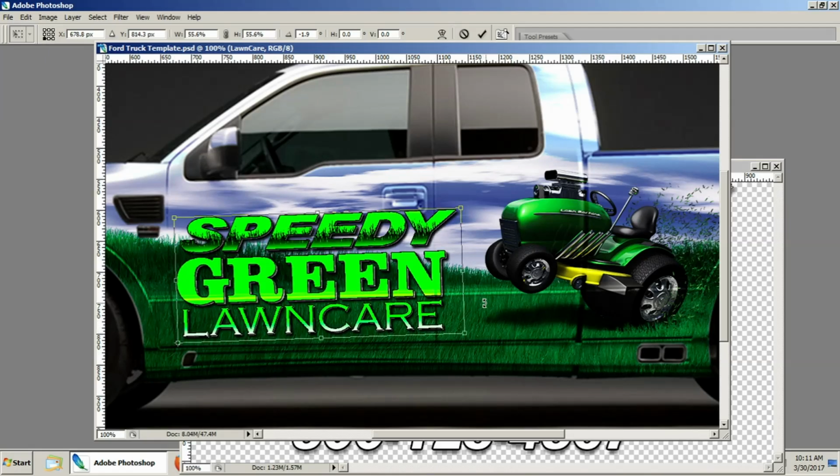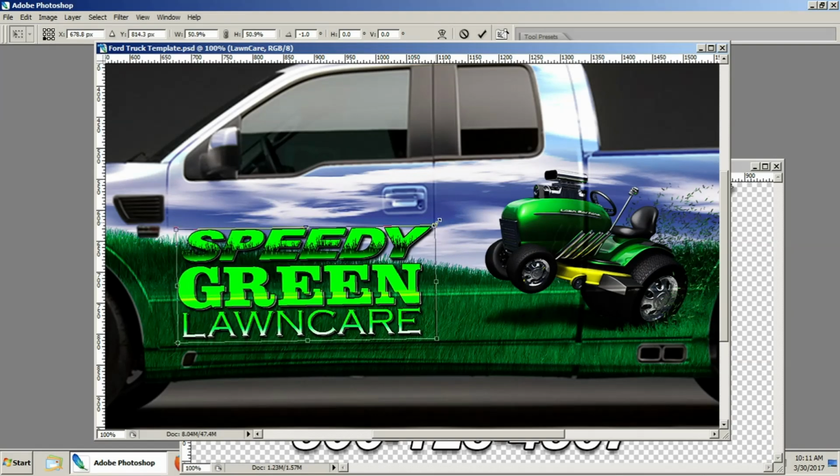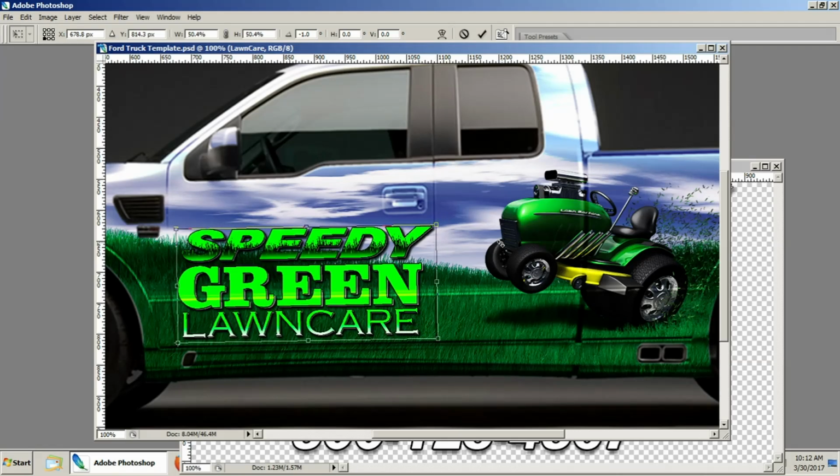Anyway, we'll stick that on the corner and go ahead and rotate and scale until it's about right, holding Shift to keep your proportions correct. And if you notice the bottom line here, that's pretty close. We'll go ahead and call that good. And before you click OK to end the selection, you want to note the rotation angle that you did and write that down. So that's a perfect -1 degree angle that we put on this logo. So we'll go ahead and write that down on a piece of paper, that's what we did, and then click OK.